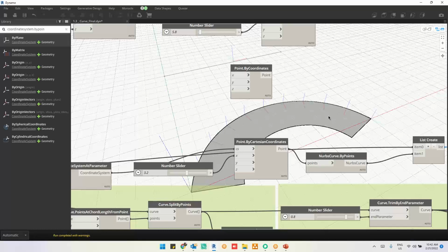If a Civil 3D coordinate is in some other position and my Revit coordinates is in some base point location, I just want to move those geometries into the Revit location. So can I move using angles if it has an angle or rotation? Yes, you can. You can change it.